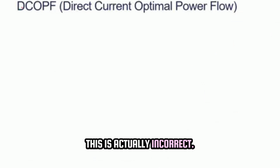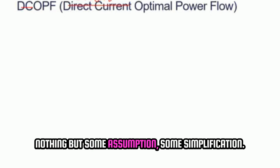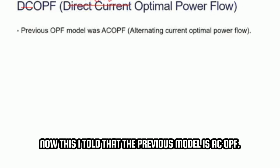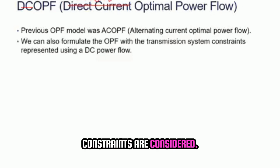This is actually incorrect. I will not call it direct current. It is called direct current in the literature, but this is nothing but a linear OPF. We are deriving this linear OPF, which is nothing but some assumptions, some simplifications we are adding to the AC OPF to arrive at a simplified version. Let us see this simplified version in today's class. I said that the previous model is AC OPF. AC is alternating current optimal power flow, because all reactive power and voltage related constraints are considered.